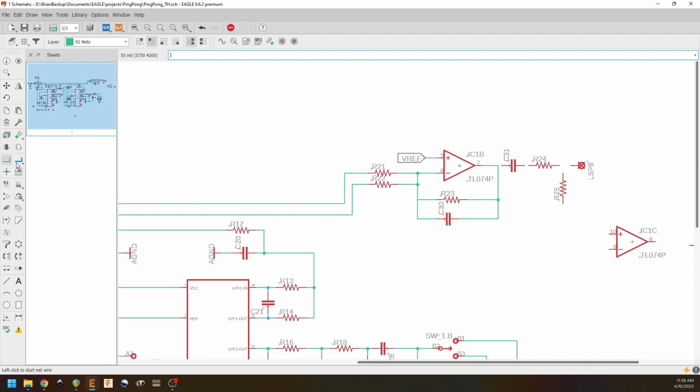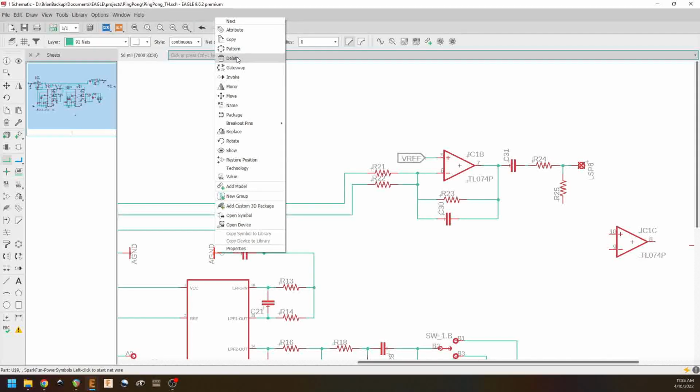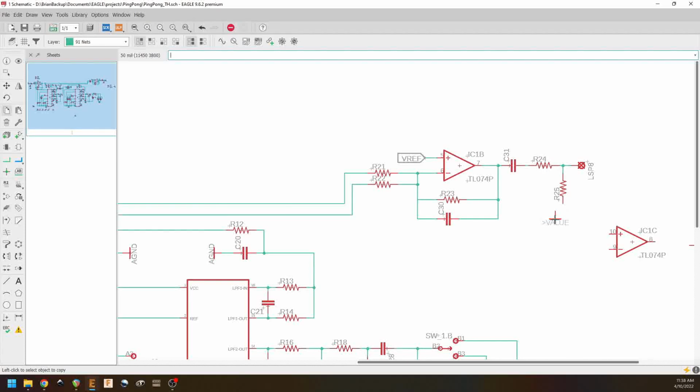It is more just here to provide a controlled path for this DC blocking capacitor to discharge when we don't have anything coming through the audio path. This will help with reducing the occurrence of pops when we switch the effect on and off, and then this guy goes to ground.